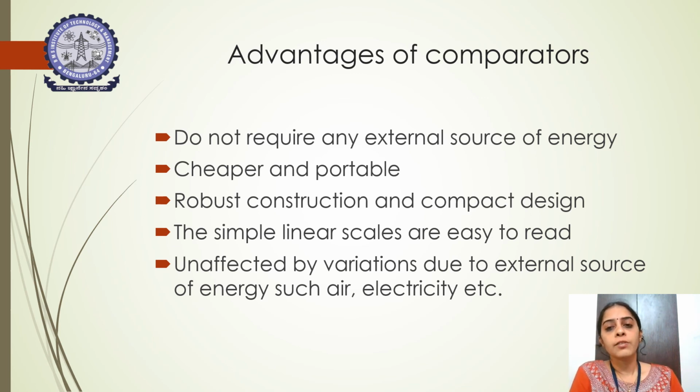Advantages of comparators are: it does not require any external source of energy. As it is told, it uses mechanical means to operate and no power source is required, and it is comparatively cheaper and portable when compared with other types of comparators. We'll speak about the other types of comparators in the next session. And it is robust in construction and very compact in design also. So the design is robust and compact in nature, and the simple linear scales are easy to read.